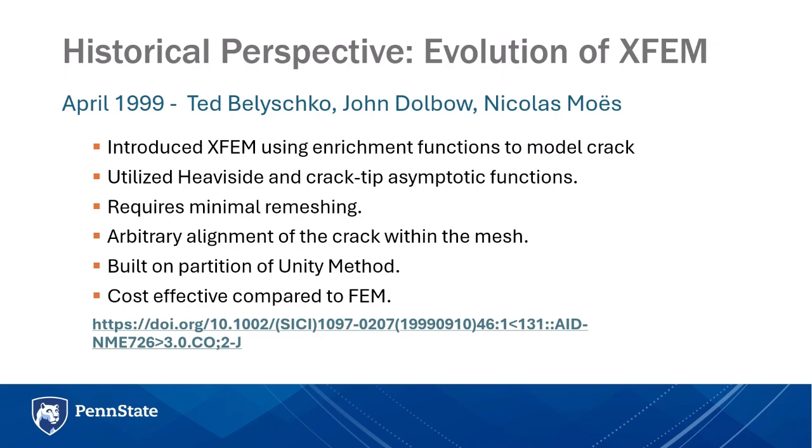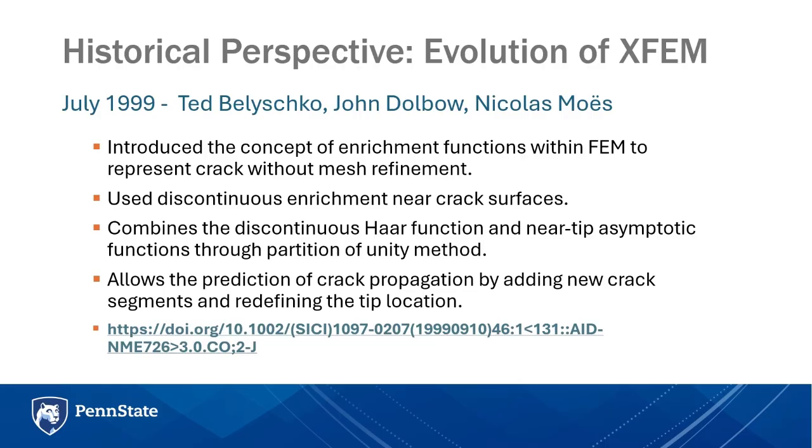And in July 1999, it introduced the concept of enrichment functions within FEM to represent cracks without mesh refinement. It used continuous enrichment near crack tip functions. It combines the continuous Heaviside function and near tip asymptotic functions through the partition of unity method. It allows the prediction of crack propagation by adding new crack segments and redefining the crack tip location.